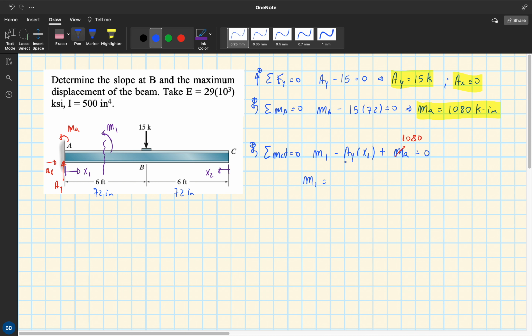I'm going to do the cut for x2 as well. If I have drawn my x2 going in the opposite direction like x1, I also have to change the way my cut works, and now the moment is going to be clockwise. In this case, I have my M2 right here. See this, my cut is this portion here that I'll be looking for, while for M1 it was this portion here.